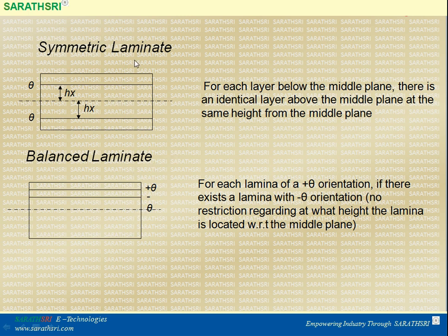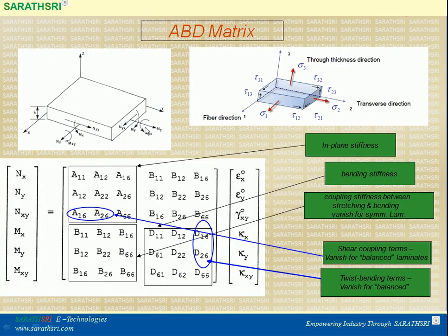Because symmetric and balanced laminates are very important, they create a comfortable position while solving the design and analysis, because placing the laminate as symmetric eliminates some of the terms, which makes it easy to analyze. Finally, the ABD matrix can be formed, as will be discussed.